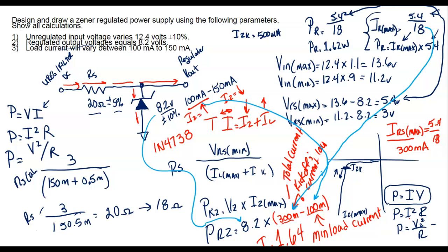What we're trying to do is figure out when the current flow through the Zener is maximum. And we know the voltage that's given. And another reason why, even if this came up with exactly 1 watt, or even around 1 watt, we would go ahead and round it up, is because that Zener voltage is plus and minus 10%.